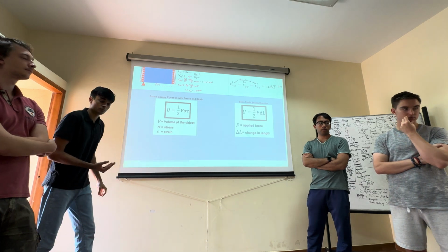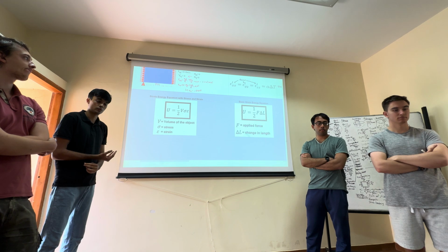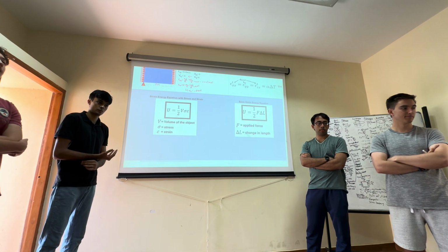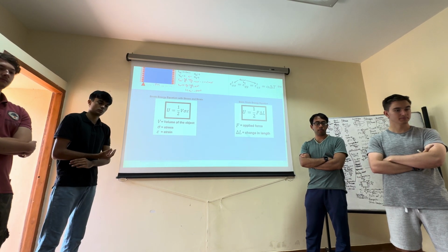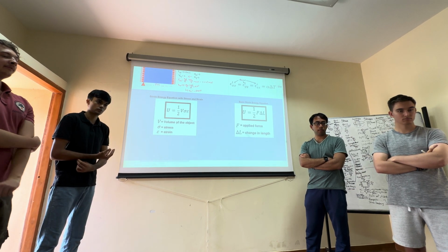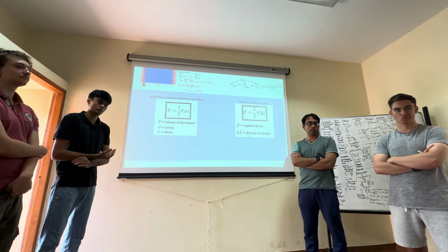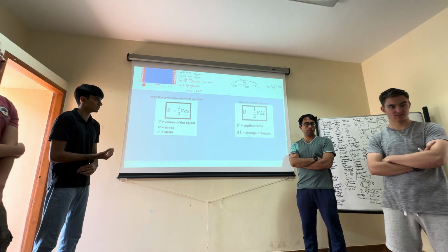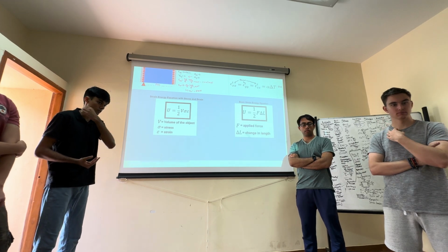These are valid if you're talking of V as an infinitesimal element, not the volume of the entire object. Remember, in the object, stress and strain are functions of the spatial location, apart from time. So it will vary from one point to another within the object. You can't just multiply the volume with the stress and the strain. Even if you average out the stress and the strain, it will not work. You'll have to actually do the integration of sigma epsilon dV. Same thing with F dx, or F delta. So it's specifically used, not just a general equation.